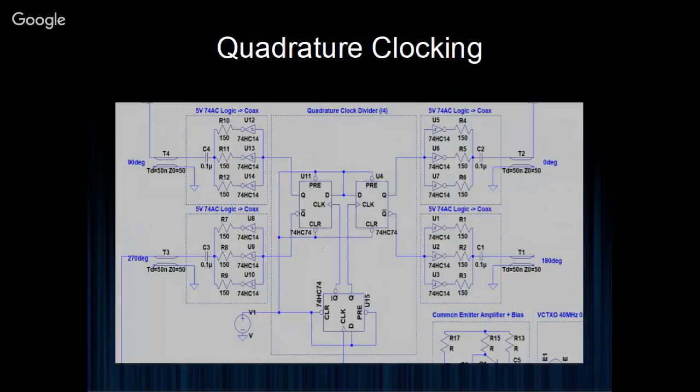So the complement is normally fed back into the D, which means that on each rising transition you have a toggling of the state of the flip-flop. What that also means is that the flip-flop is effectively a divide by 2. So if you want a 10 megahertz output, you've got to give it 20 megahertz. And the use of this flip-flop down here is sort of dual purpose. It provides the complement, but it also ensures a 50% duty cycle. And you can't necessarily guarantee a 50% duty cycle from your oscillator. It depends how it triggers and exactly when. The only thing that an oscillator really guarantees regularly is the frequency, if you're lucky.